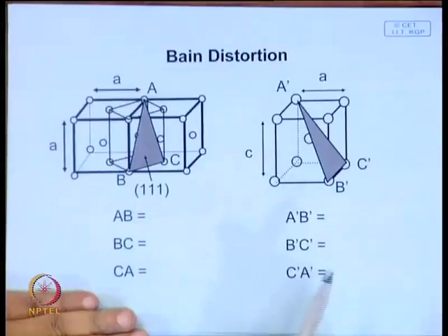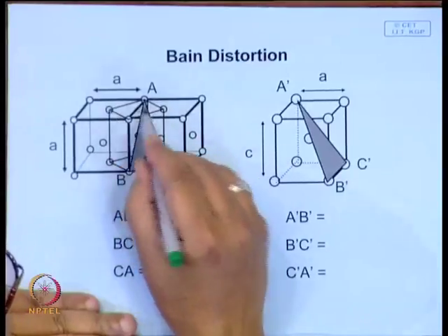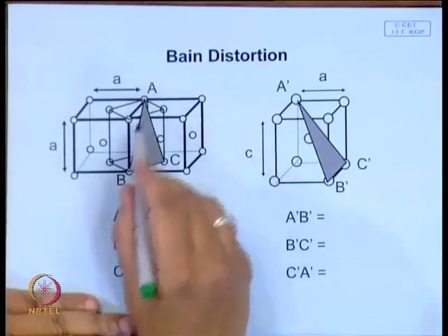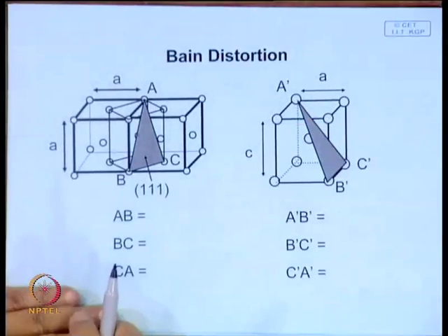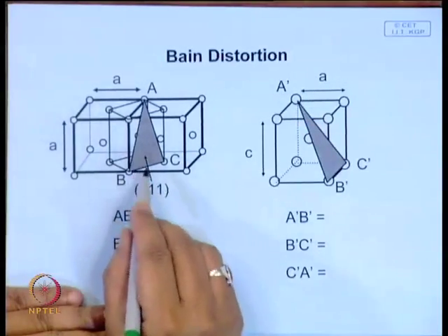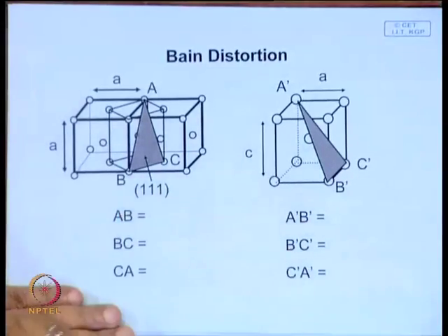Now, if this type of transformation takes place, then there are certain crystallographic restrictions which must be followed. Look at this, this is shown in the next slide. This is the cell from the previous diagram, which gets converted into a body centered structure. Now, look at the correspondences of different planes and directions in this case.